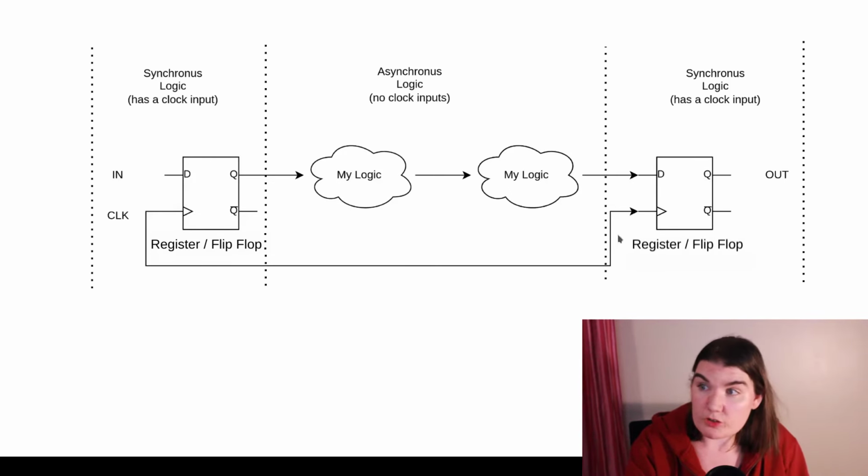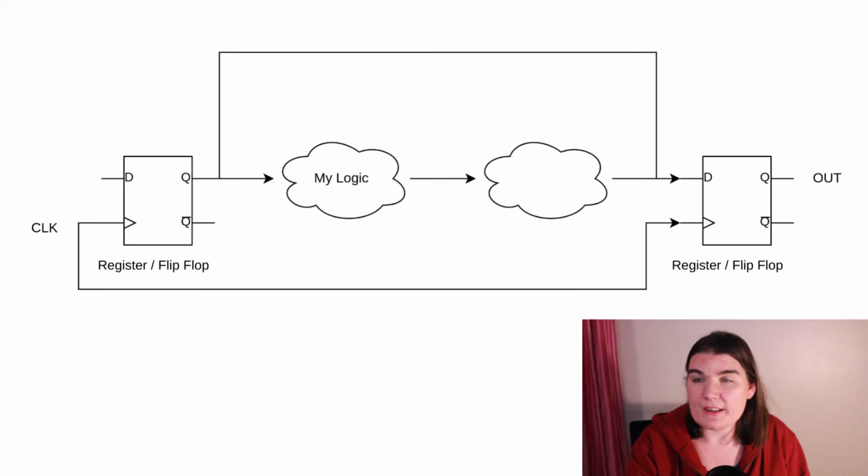So we have one clock that's driving both of these, and the static timing analysis tool is going to measure the signal distance from there to there, and also the clock propagation time, because that's also not instant. And how is it going to do that? Here. Because this path is now an unknown length. Because if the signal is feeding back on itself, it has an unknown behavior. It might oscillate. It might stabilize. We don't know. And the tool can't guarantee how long it's going to take to arrive at its destination. And that is the critical part: this delay time is now unknown.